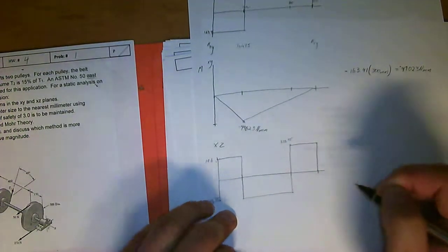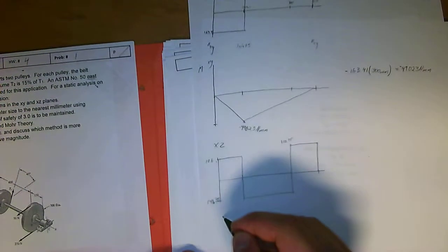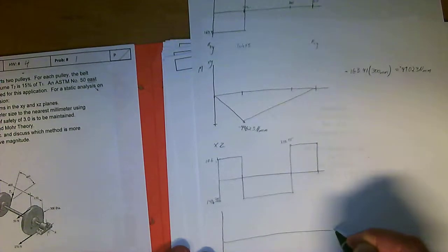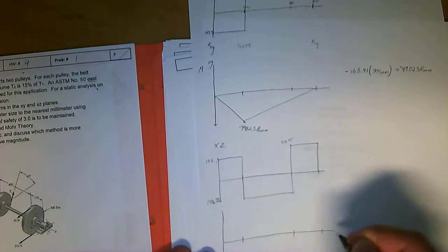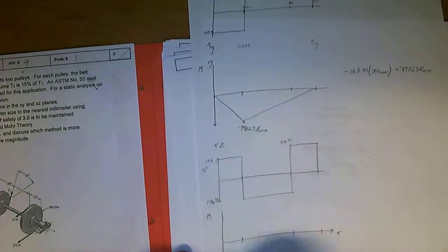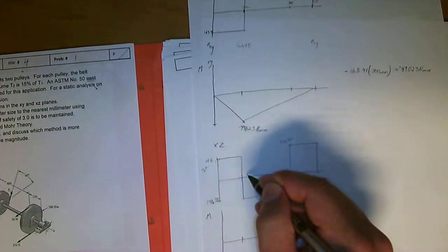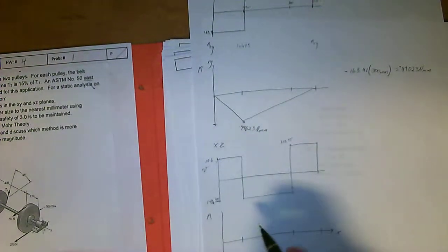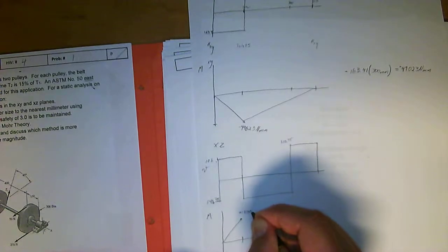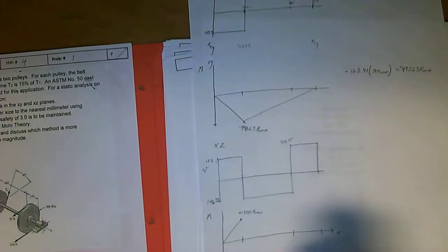Okay, and then going on to the moment diagram here. This moment diagram actually requires a little bit more math than the first one, but anyway, we'll survive. This is in the X, and then this is in the Y, and then this is the moment diagram. Okay, there we go. So, for the first one, we have a positive moment multiplied by the area, which is the area under the curve. We find the maximum value for the moment. That goes up like this, and it is at 31,800 Newton millimeters. I know it's in millimeters. I'm sorry about that. I did that calculation earlier without rounding it up, but you can fix it a little later on in the problem because it's just the power of 3. So this could be 31.8 Newton meters if you want to do it like that.